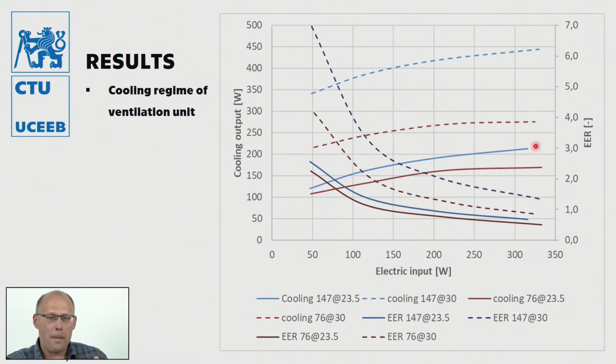What you can see also is the mentioned energy efficiency ratio. Those are other curves which start on the top on the left side and go smaller and smaller on the other side of the diagram. Obviously there is a limit which makes sense to run such a ventilation unit, and we expect the minimum energy efficiency ratio to be 1.0, the minimum sufficient ratio.